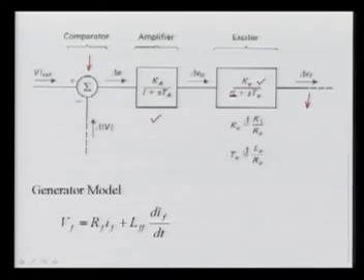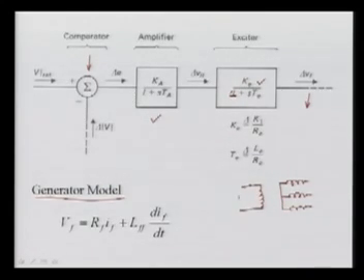So for the generator modeling, in the basic diagram of the complete AVR loop, we saw that the armature, which is 3-phase, is supplying, and the field winding is rotating, and this is the Vf which is coming from the exciter. So here we can write: if the current flowing in the field winding is If, Rf is the resistance of the field winding, and Lff is the self inductance of this winding.